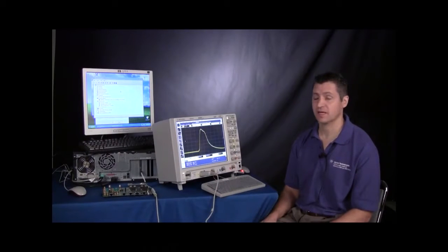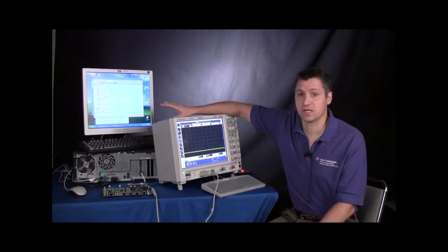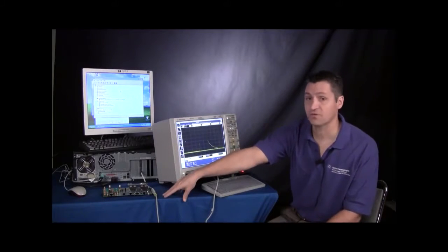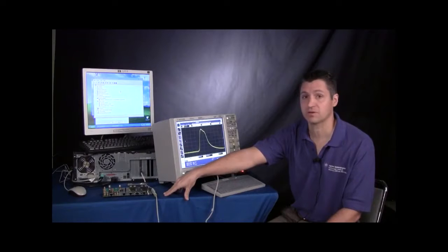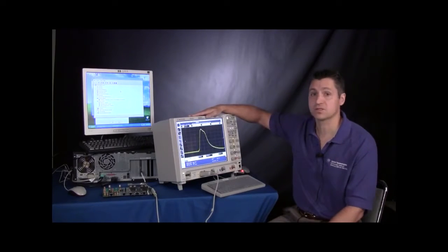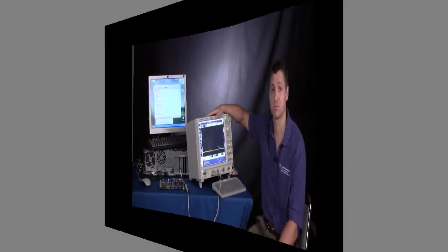So in our setup today, we're going to set up this DUT so that it can send out a consistent link pulse. And we're going to do that within the XP Windows environment. Down here on our fixture, we're going to connect a link partner to it so that we can have a consistent pulse. And over here on a scope, we're going to reconfigure it also with its Ethernet controller so that it's sending a consistent 10 base T link pulse.